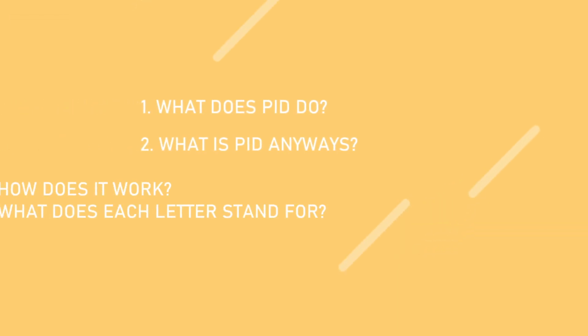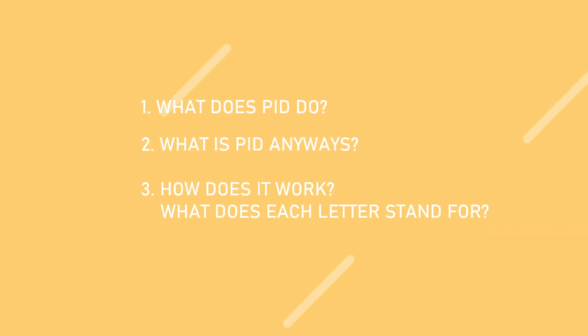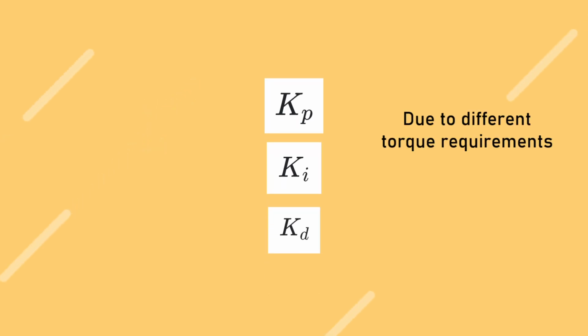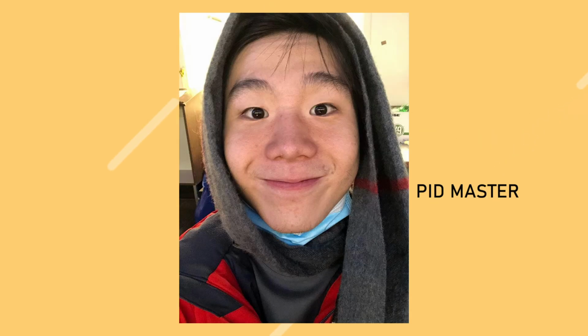These are the values I just explained in the last chapter, so check it out if you have no idea what those are. We separate these PID values for turning and going straight, because the torque required is pretty different, and it is better to have a different value for them to work better. Again, great thank you to our PID master, Jeff, for writing this code.